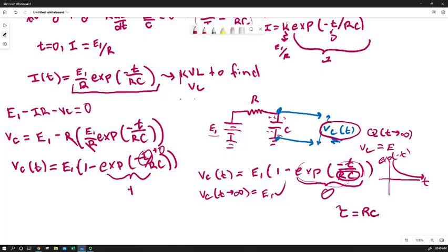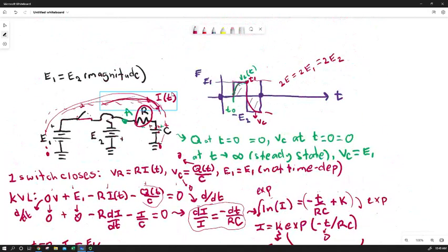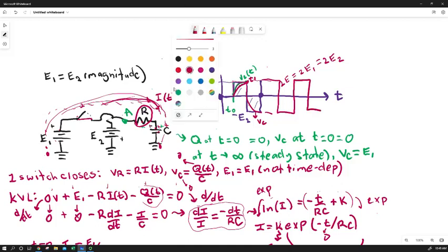And so we're going to eventually want to measure tau and relate that to R and C by measuring it experimentally. Now, one of the problems that we have is that when we apply a periodic signal, we lose this first section, because the waveform generator is just constantly giving us this square wave signal. So what we end up getting that we can measure is this part of the curve.